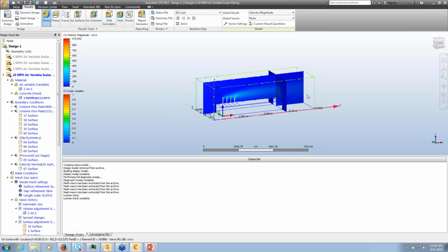Yeah. And sometimes, like I said, you might discover that the results are not intuitive, and sometimes you might discover that the air domain that I have here might not be high enough, or maybe even though it's not high enough, the results might still tell you what you want to know, without it being as high as it needs to be.